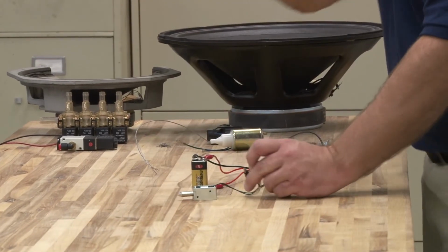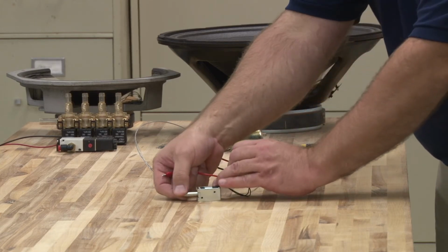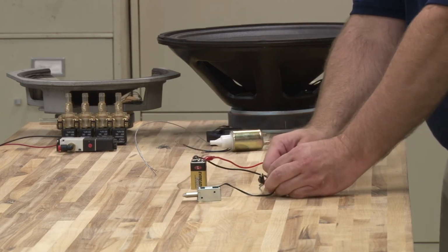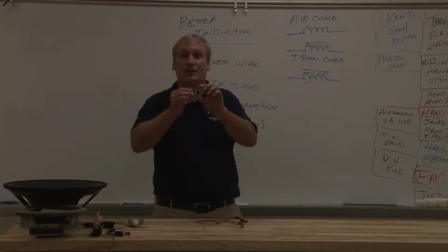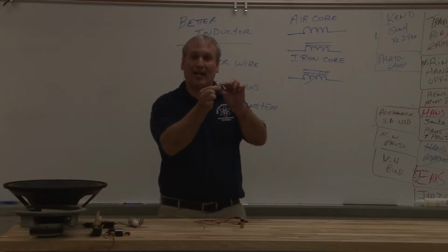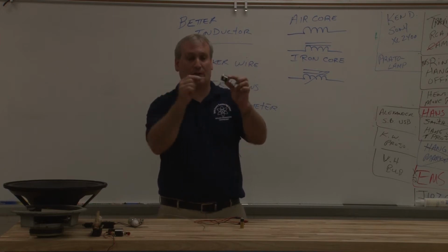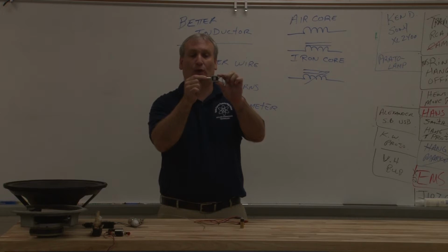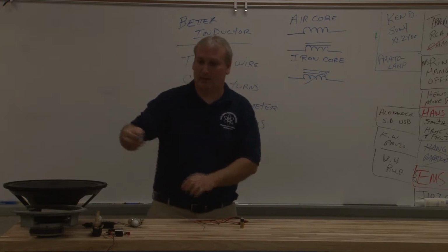So if I need to move a latch or a lever, I hit the solenoid, the electromagnetic field builds up and pulls the lever in. I'll pass this around so you can look at it. What's under this black tape is what? A big coil of wire. This will fall out, so let's not lose that. When you energize the coil of wire, it pulls that in. Does that make sense? Taylor?